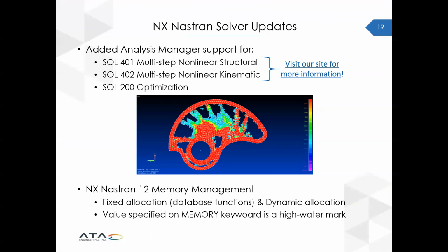In addition, NX Nastran 12 brings some new memory management. So now we have both a fixed allocation, which would be our database functions, as well as dynamic allocation. So what we would see is if we specify a value using the memory keyword, this is now a high watermark.